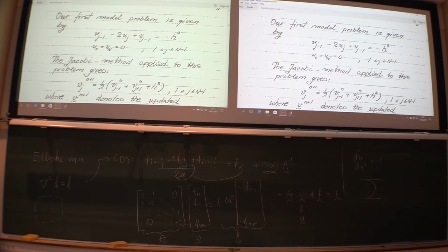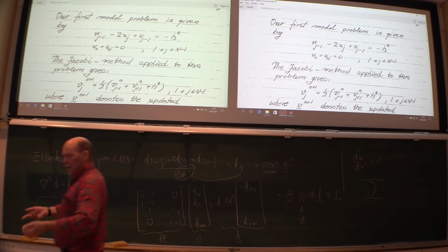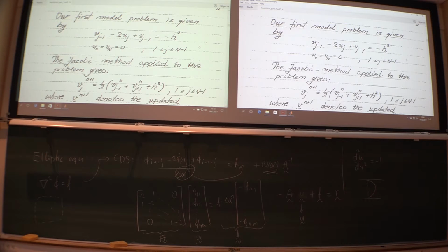Later we are going to use the same equation, but then in 2 dimensions, sort of the flow in a square duct. So you have a double derivative in both the x and y direction. Also, we are going to look at an equation system where we say the right-hand side is 0. Then we are searching for, say, a dummy solution. Then we know the solution is 0, and the reason to do that is any difference from 0 is an error. So that's quite convenient when you want to investigate how the error changes. But you'll see that later on.